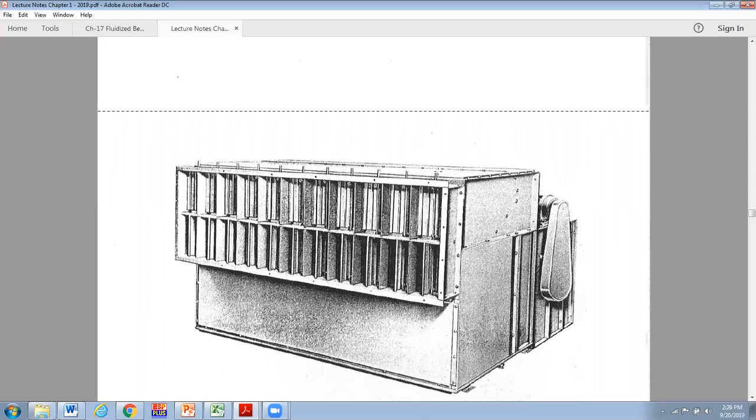And then these little posts that stick up, they control the dampers. So if they rotate one way, you get all hot air, and that closes off the cold air. If they rotate the other way, it's vice versa. You would get all cold air and close off the hot air. And then the thermostat would position the controller so that we get the right temperature of air to keep the space comfortable. So you can have big spaces and little spaces.